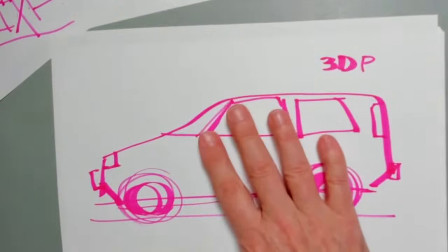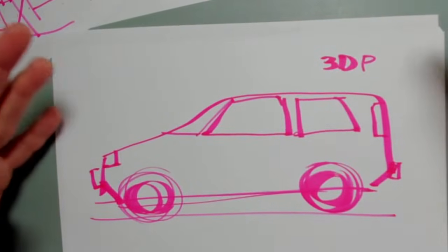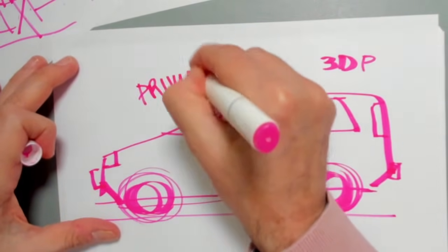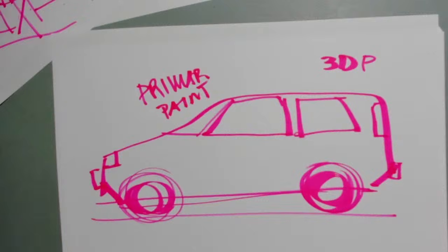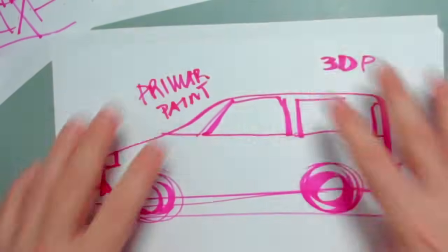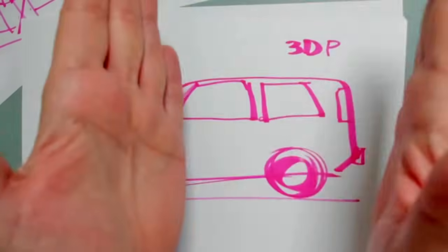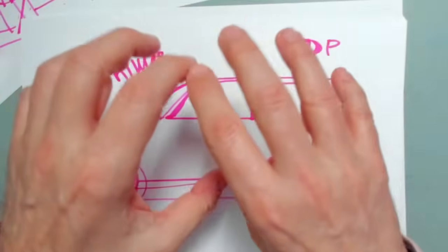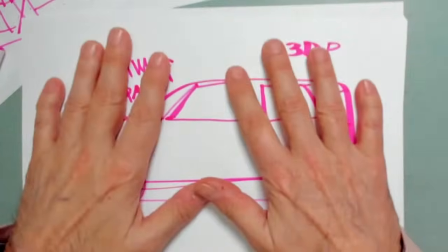Here, when it's a clay model, first we put it in the spray booth, the big one, and we apply a sort of primer paint all over. And this primer is gray color. Now, why do we put that primer? Because that primer is made with chemical elements inside that will stick to the clay, because the clay is like oil. So you have to apply something that will really glue to the clay, unless everything will come off, and you don't want to have that. So the primer is the first thing.